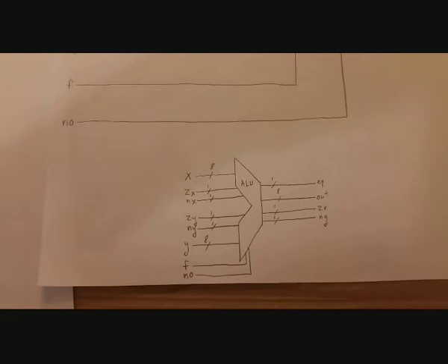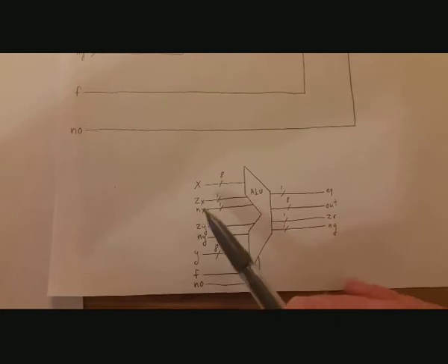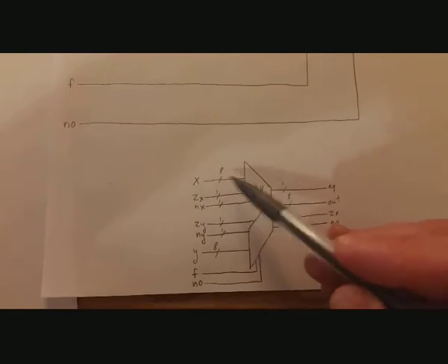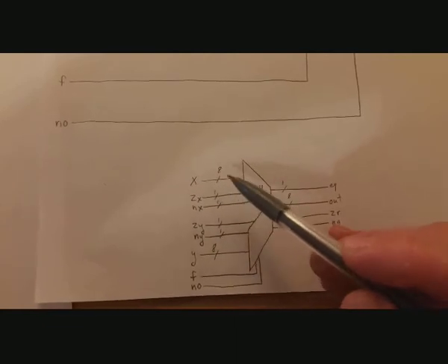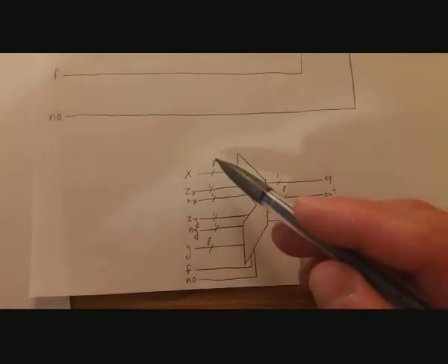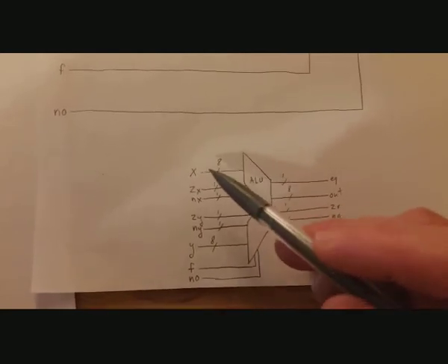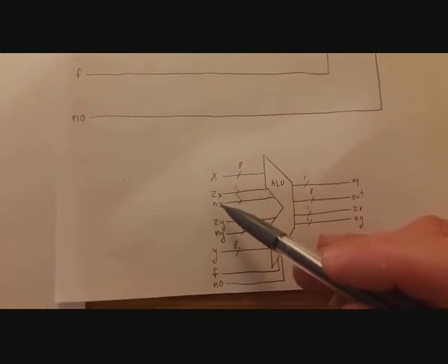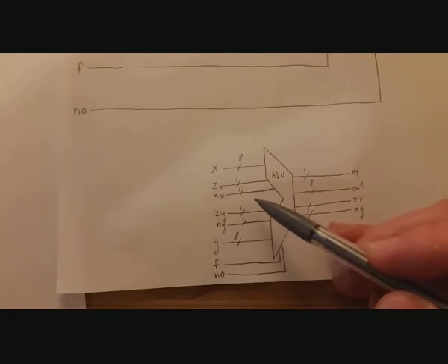And just to show the ALU again, we're going to have X and Y. And the notation for this too, these are wires basically, right? So this is an input value X. Here's a wire going into the ALU. It's just black boxed right now. The /8 here means this is actually a bus, eight wires wide. So those are going to be all the bits of X. And then we have that ZX and NX. Those are one bit each, so these are just singular wires.